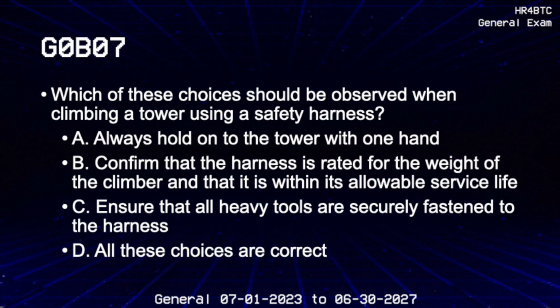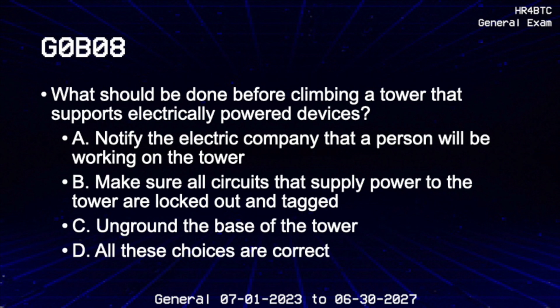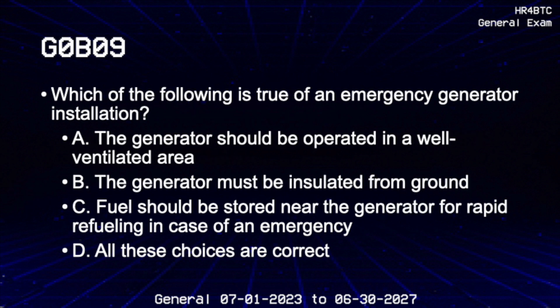Which of these choices should be observed when climbing a tower using a safety harness? Confirm that the harness is rated for the weight of the climber and that it is within its allowable service life. What should be done before climbing a tower that supports electrically powered devices? Make sure all circuits that supply power to the tower are locked out and tagged. Which of the following is true of an emergency generator installation? The generator should be operated in a well-ventilated area.